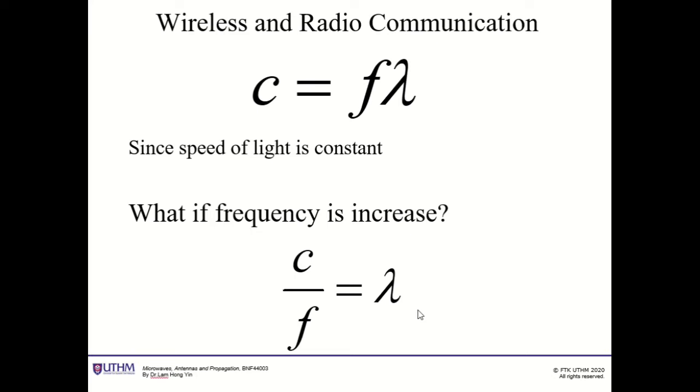If you look at an antenna, for example the Yagi-Uda antenna, or you call it a fishbone antenna, the frequency is around 400 to 800 megahertz. That's why the antenna is big, because at low frequency lambda is increased. The antenna depends on the value of lambda, so the larger the lambda, the larger the antenna.